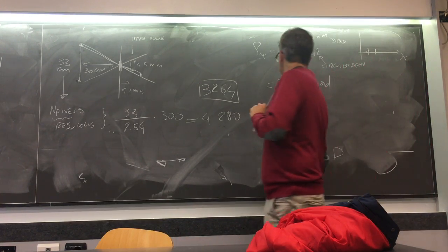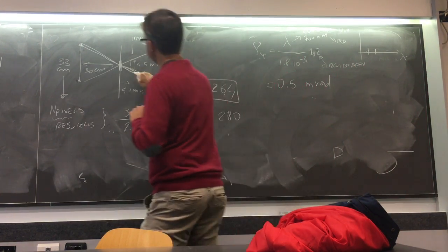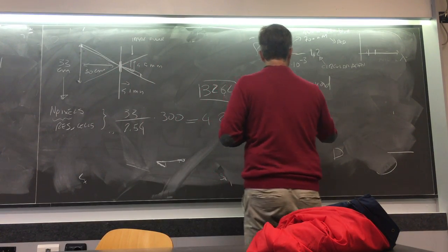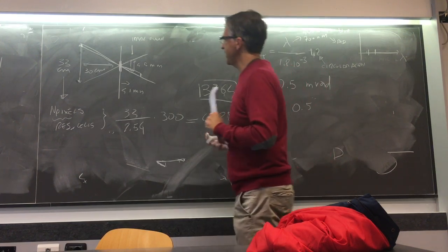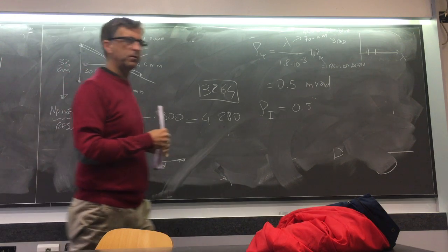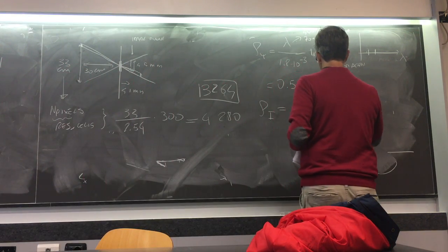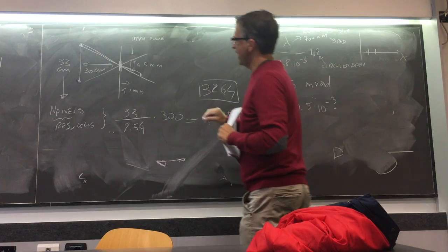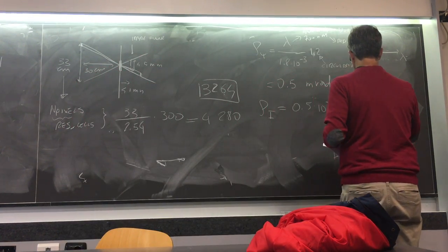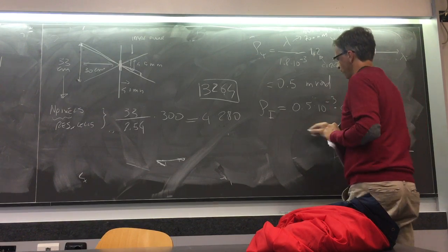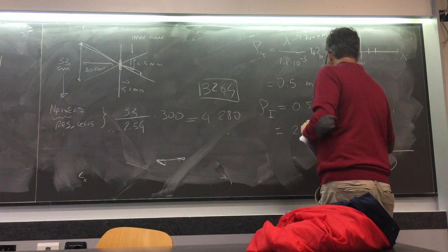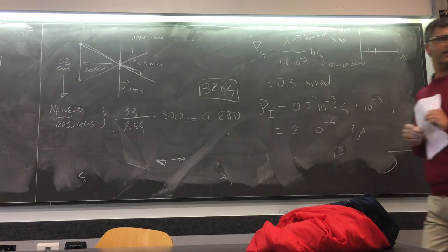Well, if you consider this, and then we consider a resolution cell on the image, that is 0.5 milliradians multiplied by the focal length, that is 0.5 10 minus 3 multiplied by 4.1 10 minus 3, that is a focal length, and this is approximately 2 10 minus 6, is 2 micron, okay?